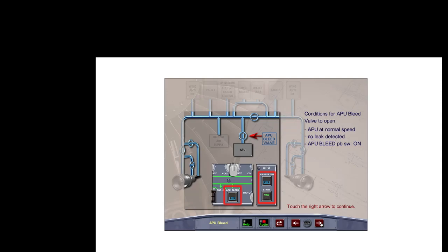Conditions for the APU bleed valve to open are that the APU must be operating at normal speed, there is no leak detected, and the APU bleed push button switch is on.